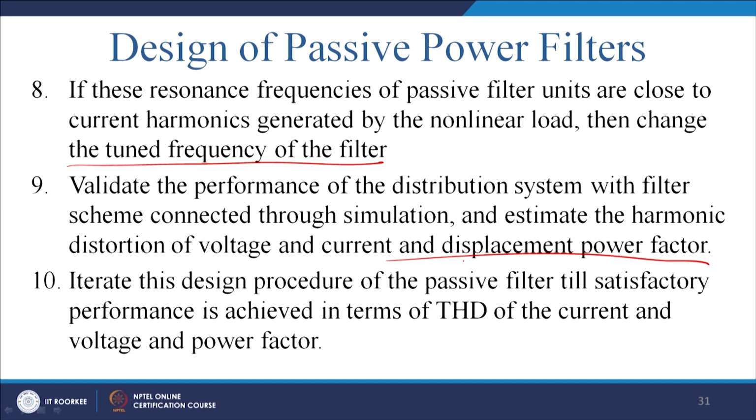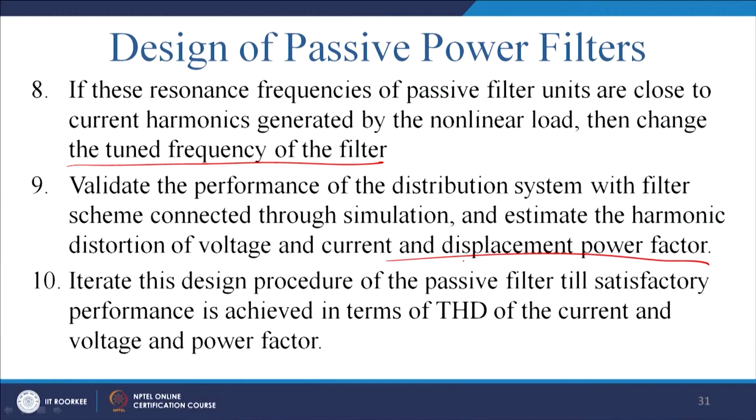Sometimes it is challenging. You can improve the power factor with source inductance. For example, you have seen source inductance improves the displacement power factor, and thus directly it reduces the value of the THD. But on the other hand, it will degrade the power factor. So, for this reason we may have some conflicting combinations.